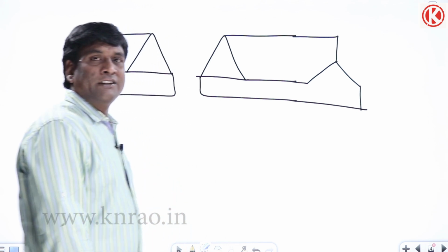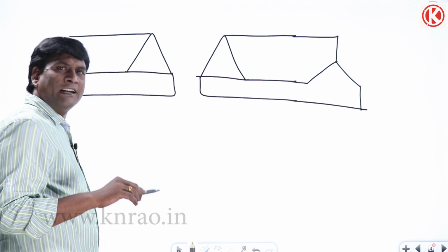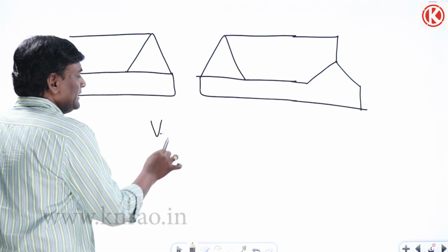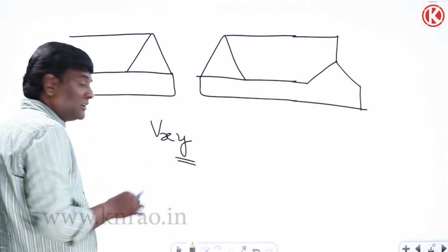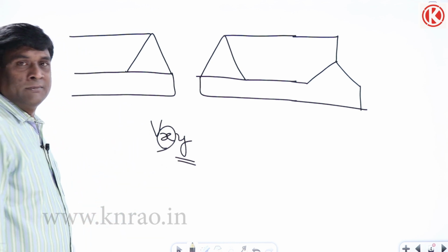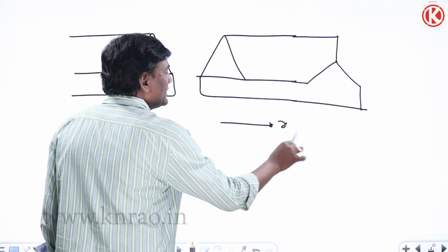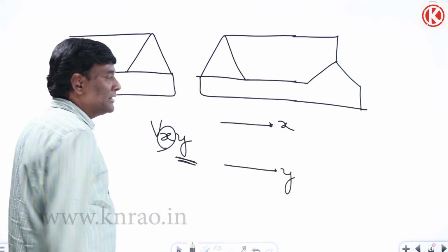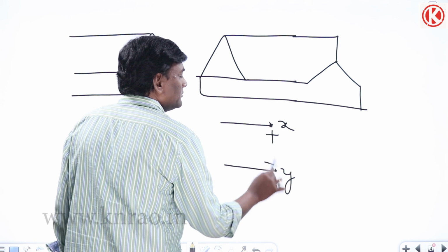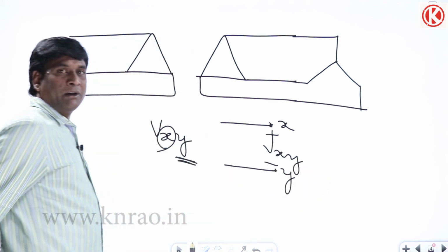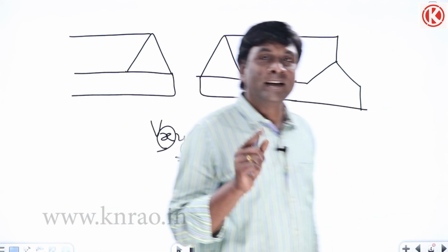Okay, if it is connected with a star connected load, one thing here, which I have already said multiple times in networks: if I write Vxy, what does it mean? With respect to y, how much is the potential of x? For example, Vxy, if this is x, this is y. With respect to the second letter, how much is Vx? This is going to be Vxy. Because polarities are very much important in representing voltage, and direction is very much important in representing current.